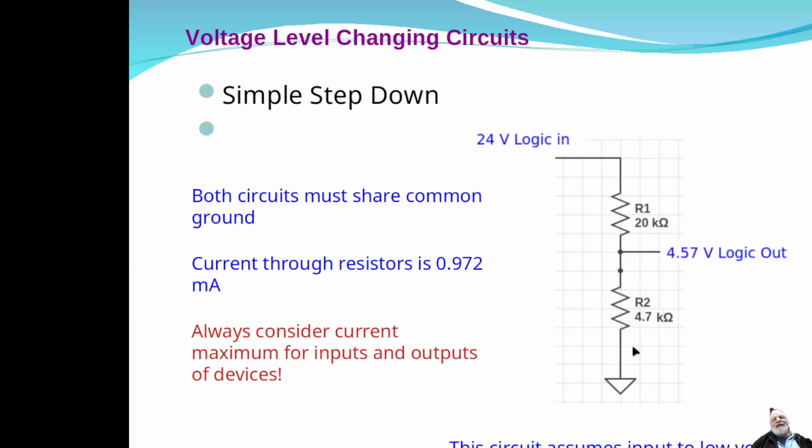So at least the sum of these should be at least 10K kind of area, 8.2K or above would be my recommendation, so that you don't waste a lot of electricity just in this switching circuit.